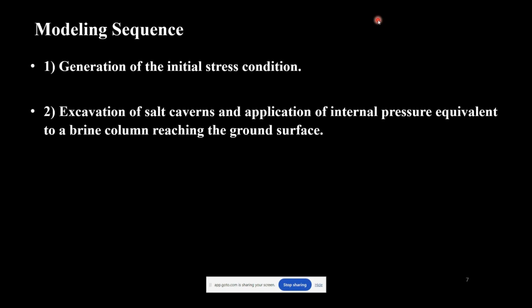Then in the second phase, I simulated the excavation of the salt caverns, and I applied an internal pressure which is equivalent to a brine column reaching the ground surface. So we are assuming that the well at the cavern is filled with brine, right? And this is also a quite typical assumption. Just remember, brine is water fully saturated with salt. Usually these salt caverns are filled with brine, right? They are not empty.